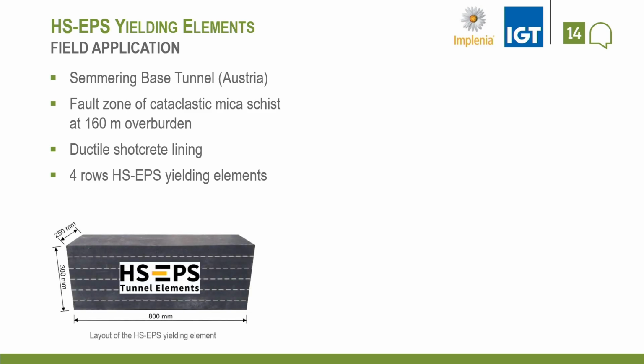This is the prototype we produced. You can see the length of the yielding element is 80 centimeter, capable for 1 meter round length, because you also have the lattice girder. It's 30 centimeter in height and 25 centimeter the thickness according to the shotcrete thickness.